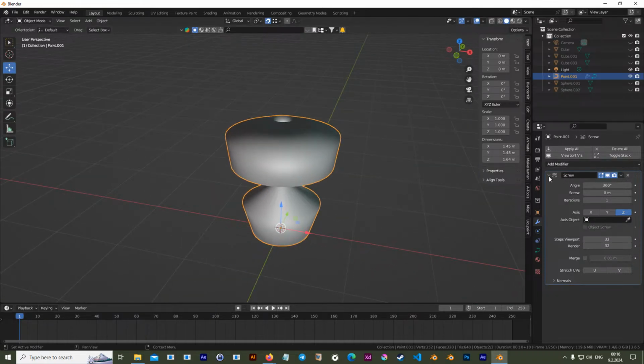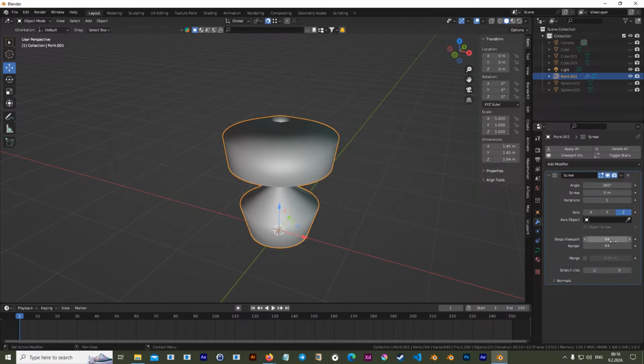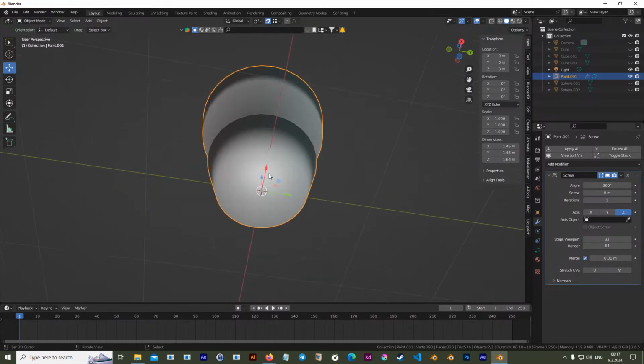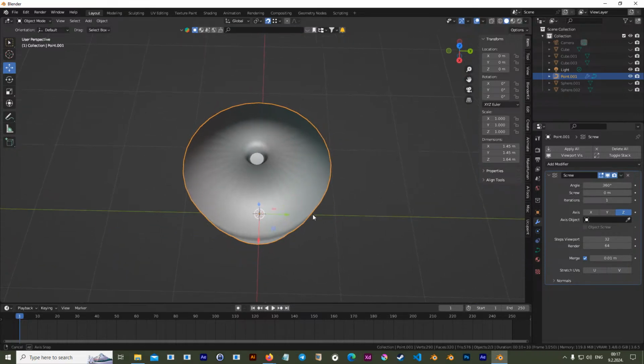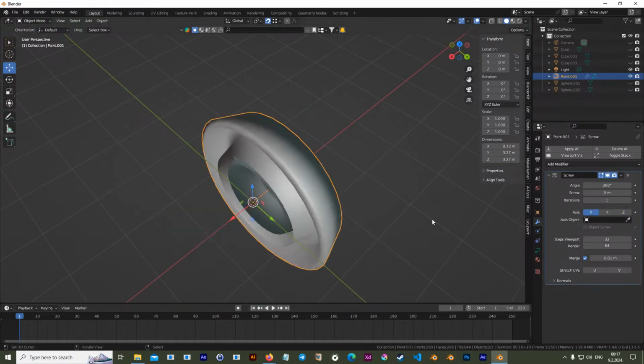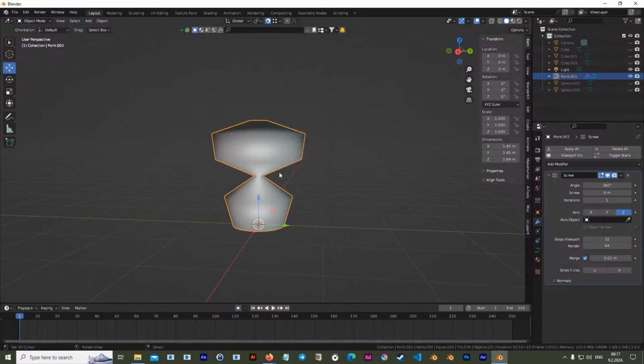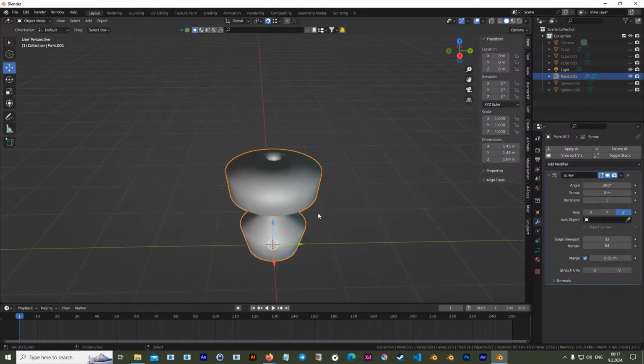If you leave your object with screw modifier, don't forget to enlarge those segments for render too. You can maybe work with 32 and have 64 value for rendering. It can merge things, and that's a good thing to check. It can merge. It can screw on various axes, but most obvious is upwards pointing one, Z.